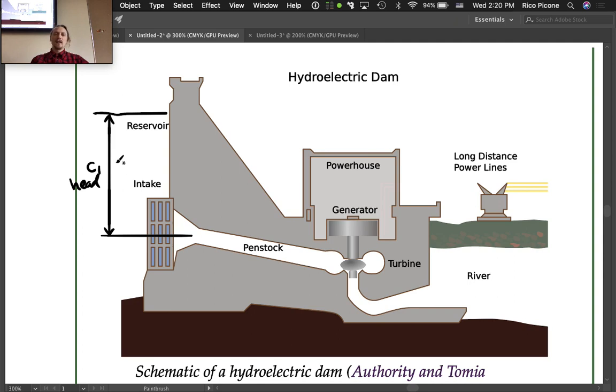But since it's something that is going to change in height, like every reservoir does change in height over the course of a year. I mean, if you go over Snoqualmie Pass, you see the nice, beautiful lake, and then by the end of the summer, you see a nice swamp with stumps out in it. It's weird. So it's the snow melt, and it fills it, and then it's gone. So this is going to change. This pressure head is going to change throughout the year, so we should model it as a capacitor, because this head will change.